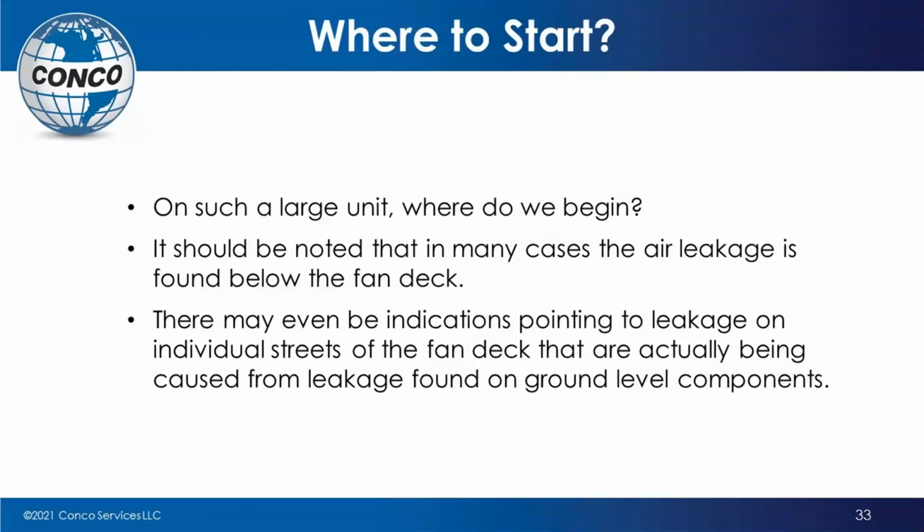And so, a good place to start is to look below the fan deck to make sure that the leak is picked up there rather than go up on top of the fans themselves. We run into a lot of instances where the indication is that the leak is up on the street when in actuality it isn't. It's down on the ground level components. So again, an experienced technician can save you a lot of time and a lot of money in finding that leak.